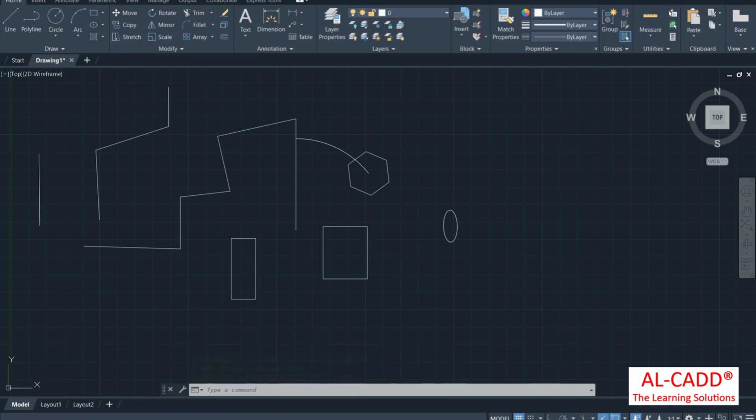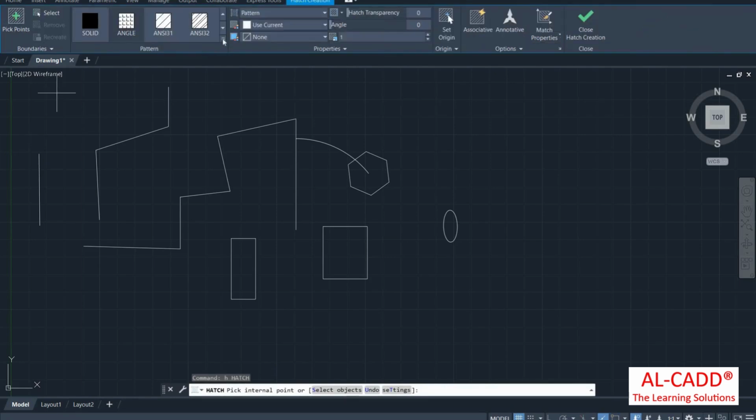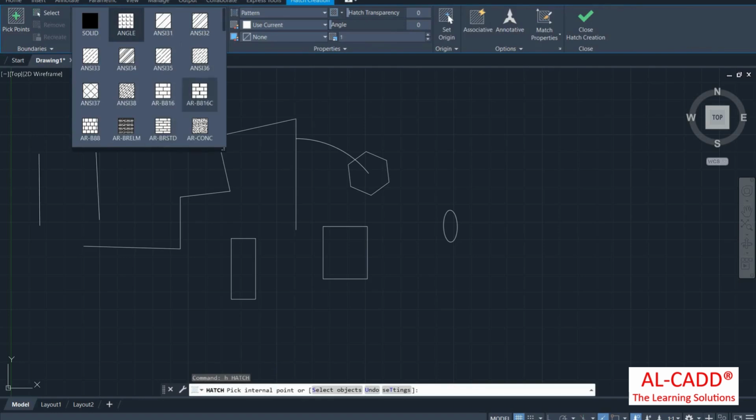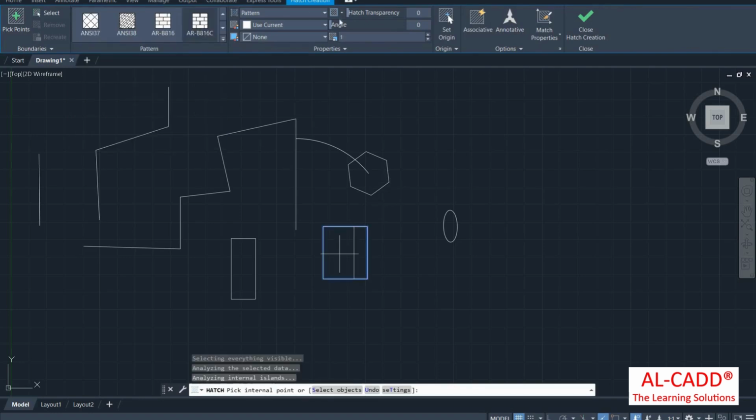Hatching stands for H, enter. Now see, if I enter H, now you can select the pattern for the hatching, whichever hatching you require. Then after that you can assign. If you assign this, make sure that the hatching scale is very large here. So if you want to reduce it, you can reduce the scaling for this.